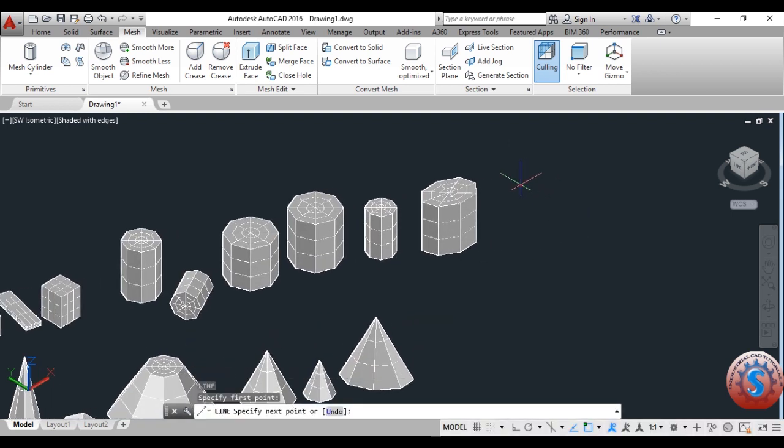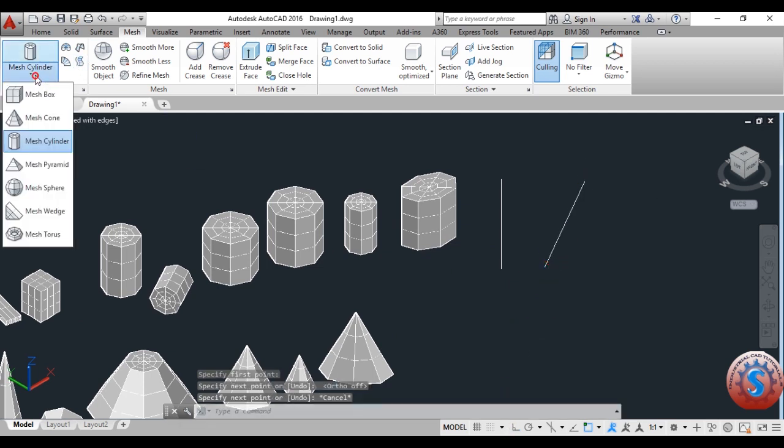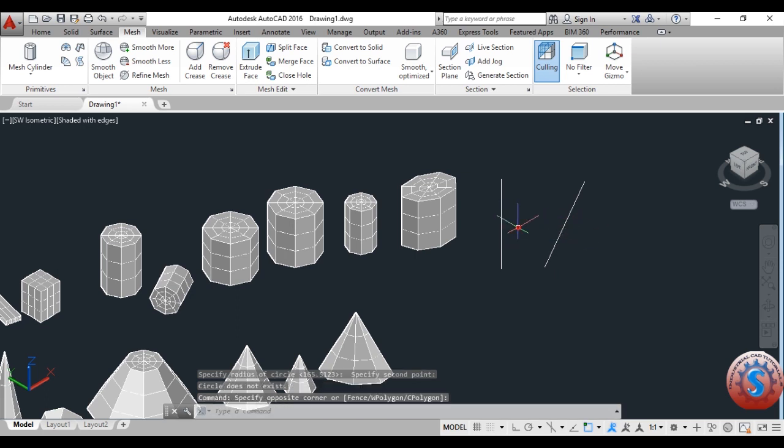These are the simple basic tutorials for the beginners I'm explaining. I have uploaded nearly 130 videos about the basic tutorials for beginners. And you can observe the tangent, I will explain. See, you can observe the tangent, second tangent. Click enter, and it asks the radius. Simply give the radius anywhere you want, then one circle will be created by using the tangent.